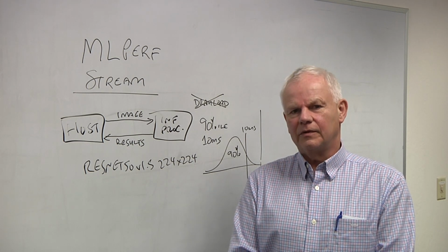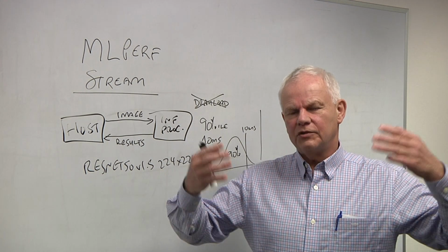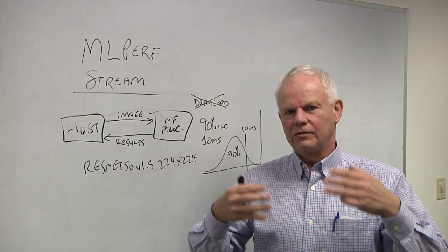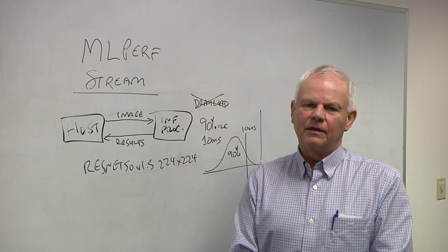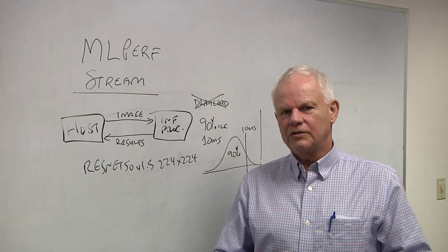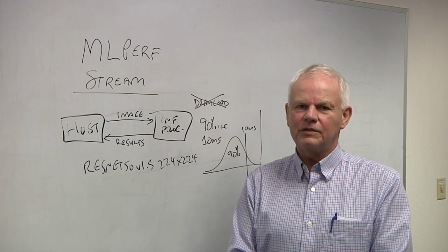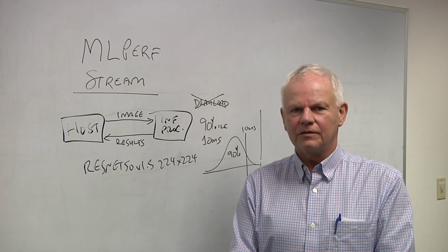If you look at chips from NVIDIA and Habana Labs today, they have 8 DRAMs, 256-bit buses. So these people are going to go to HBM memories and integrate them into the package, but it's very expensive. But it allows you to get higher frequency. Some of us are taking another direction, which is to minimize memory to get high performance. And I think in the end, for the bulk of the market, that is going to be the winning solution.